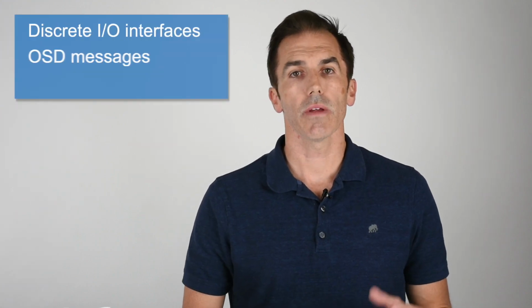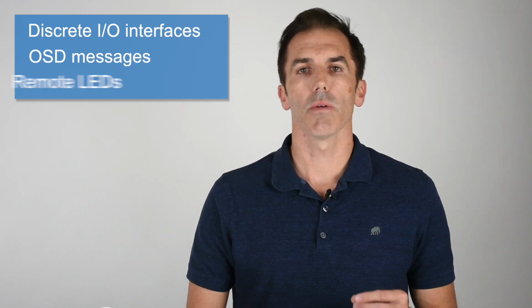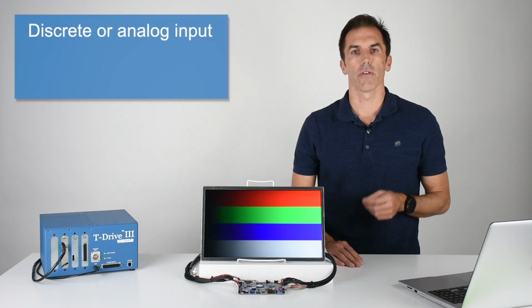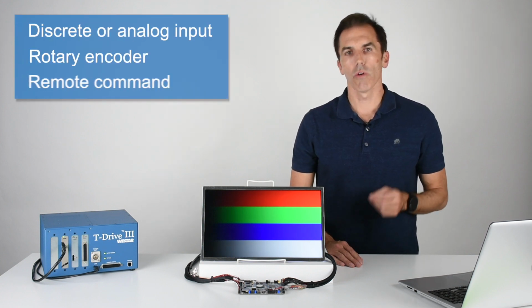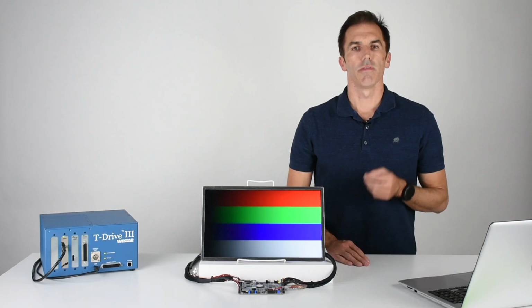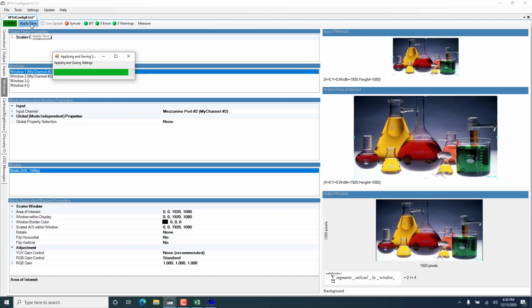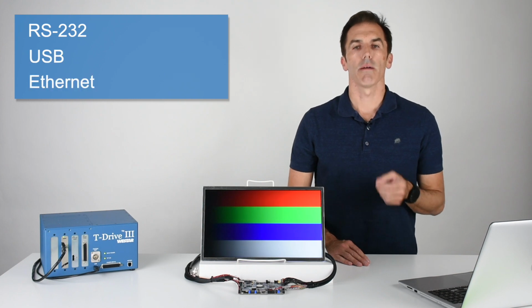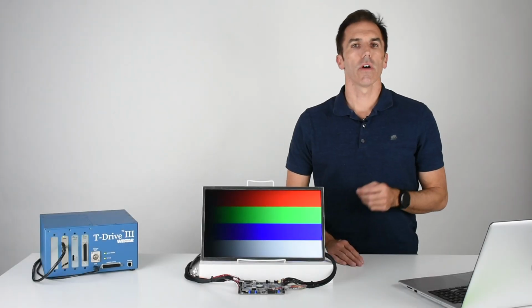The VP14 also includes discrete I/O interfaces, on-screen messaging with built-in font generators, and remote LEDs for board and video status. Video contrast and backlight can be controlled via discrete or analog input, rotary encoder, or remote command. The VP14 packs plenty of features for video processing such as windowing, resizing, and area of interest control, just to name a few. Some of these, which we will demonstrate here in a minute. The VP14 comes with configuration software used for setup, and can be dynamically controlled via RS232, USB, or optional Ethernet. That's a quick overview of the VP14.